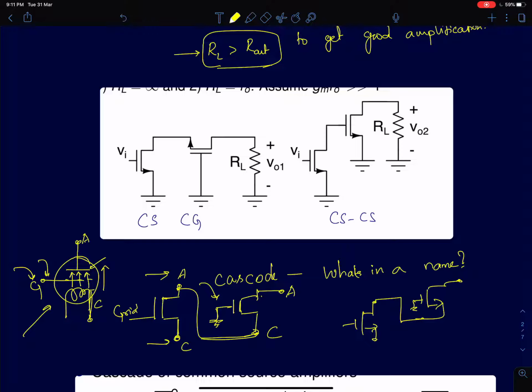So that's why it was a cascade of anode and cathode. There is an anode and a cathode, so the word cascode comes from joining the 2 words. That just distinguishes it from the regular cascade of common source stages, or anode going to the grid. There is also another explanation, where there was a device called a pentode, which had a very similar structure to this.